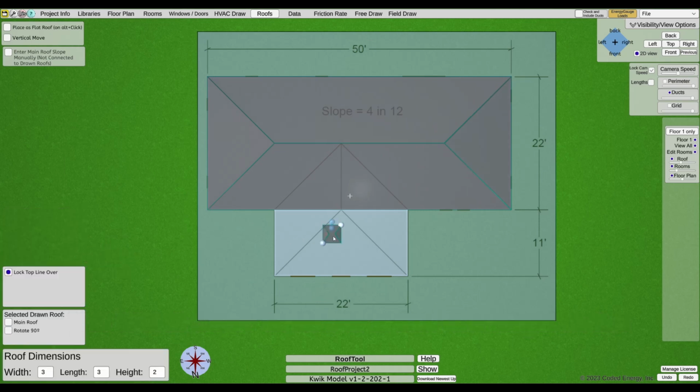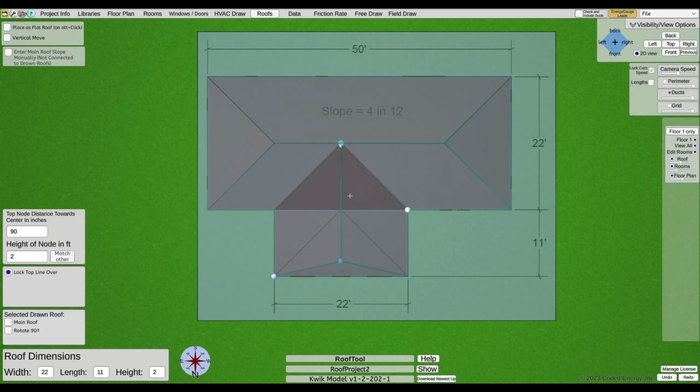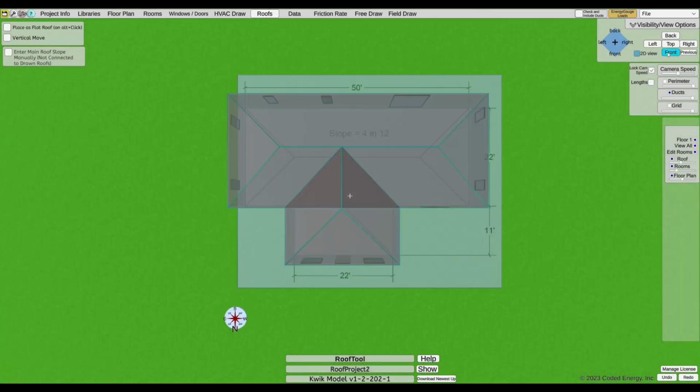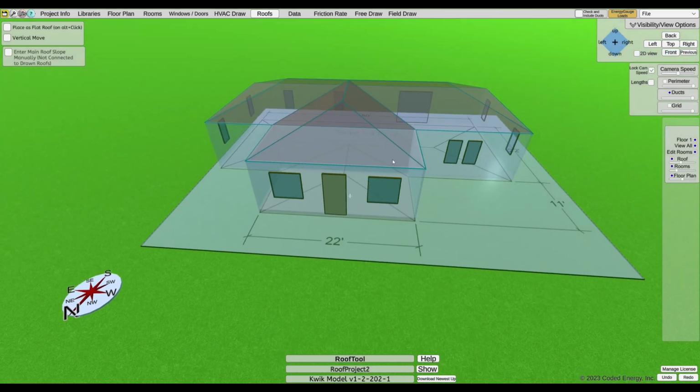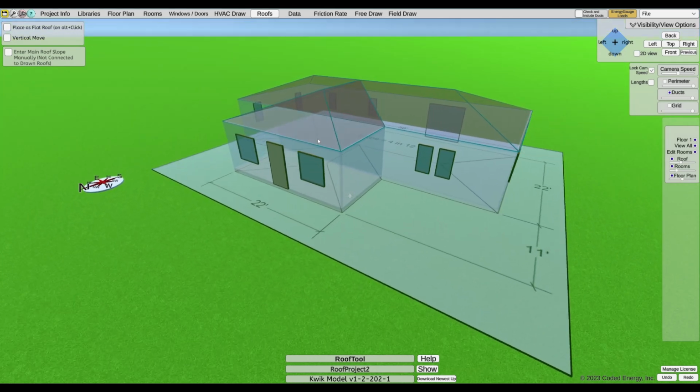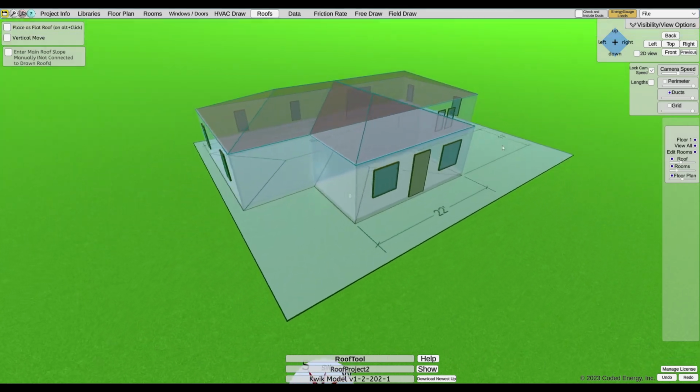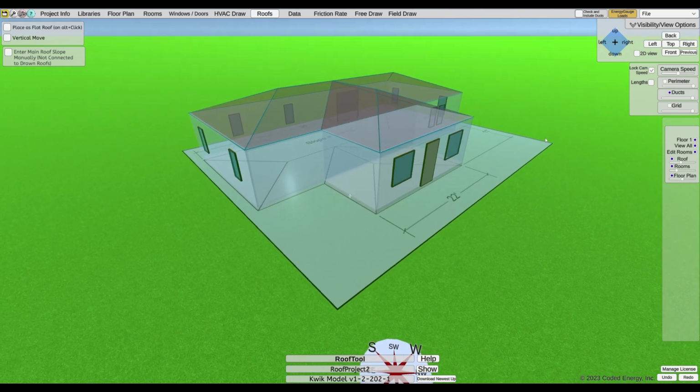feet. And we're just going to add the second one down here. Once again, just grab the handles, drag them to the corners like so, and then adjust these roof pitch handles and give it a height of 4 feet like so. And go back, make sure that roof is the main roof. Alright, and that is the roof for this project. Very simple, just add 2 roofs, line them up properly, give them the right height.